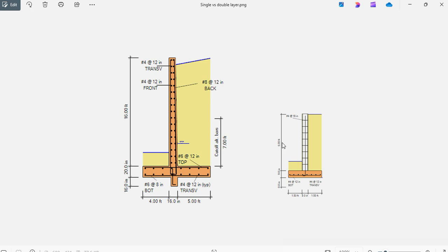But for much smaller retaining walls, like the one shown at the right, which is only 6 feet high, this is mostly done in masonry for simplicity as well. But the footing for these kinds of walls is also much smaller, probably 9 inches thick or 10 inches thick or so. So 2 layers of reinforcement is probably not necessary and will increase the cost of this kind of retaining walls. I have prepared an example for a wall similar to this one in ASDIP RETAIN.